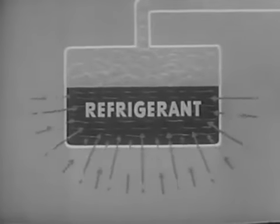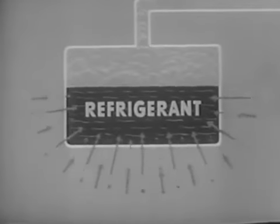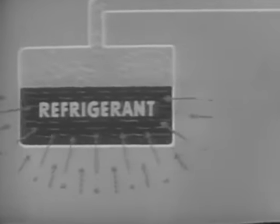The principles of refrigeration are physical principles applied as follows for the purpose of removing heat and reducing temperature. First, mechanical refrigeration rests on the ability of a refrigerant to absorb heat while changing from a liquid to a gas, and to release that heat while returning to the liquid state.